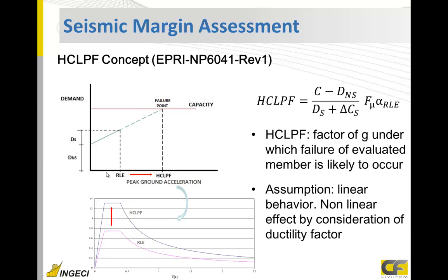If you apply a seismic analysis, a seismic load, which could come from this pink spectrum or any other type of seismic analysis, it gives you the addition of those, which is this point. It means with the non-seismic loads plus seismic loads, you have this in-plane shear force, for example, which corresponds to this seismic level. In the horizontal axis, we plot the seismic level.